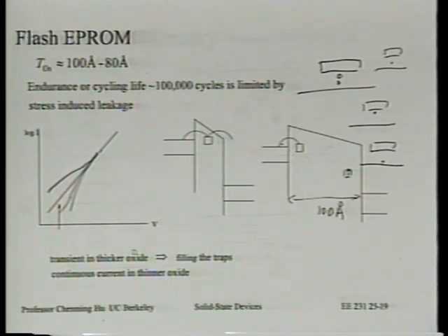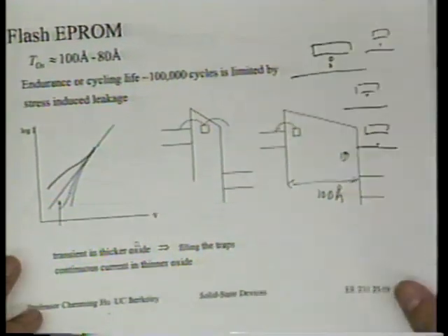It's hard to design a short channel transistor with the thick oxide, and it takes high voltage to do erase if the oxide is so thick. How can very thin oxide periphery transistors support high voltage? So it's very difficult. So far we just do that by designing high voltage modules to modify the logic technology and use thick oxide transistors to do the addressing, for example. And so people would like to look for some other ways to get around this.